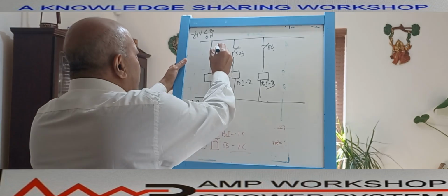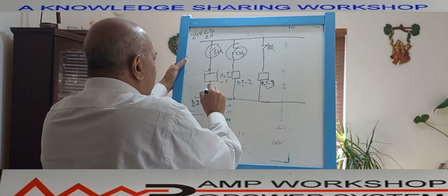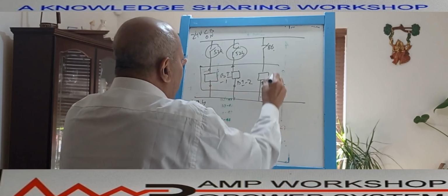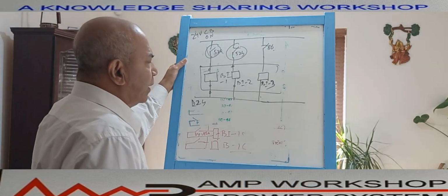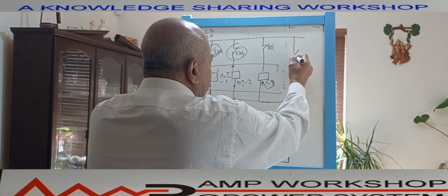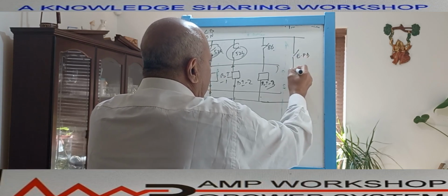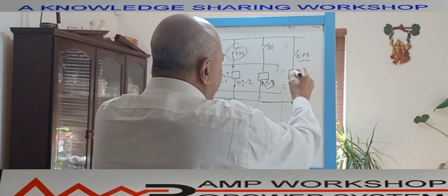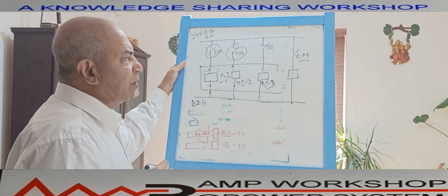These contacts are in the switchgear devices, and this is in the relay. So this is a terminal over here. These are all terminals inside a relay input card. So from the field, from the breaker, this contact will be wired up over here. Similarly, imagine a push button operated. This is the push button NC contact. When the push button is operated, I will energize one of the inputs. The moment the push button is operated, immediately this input will be high, and the relay will understand the push button is operated.